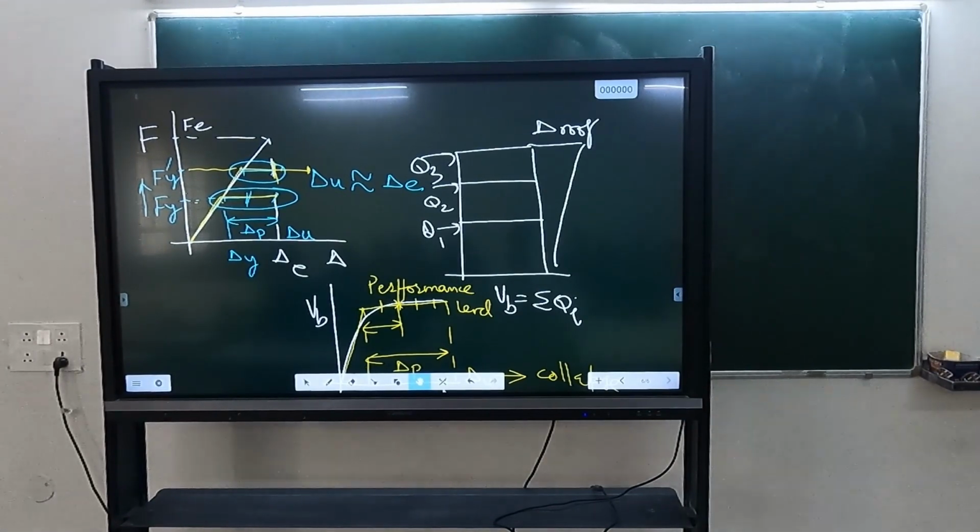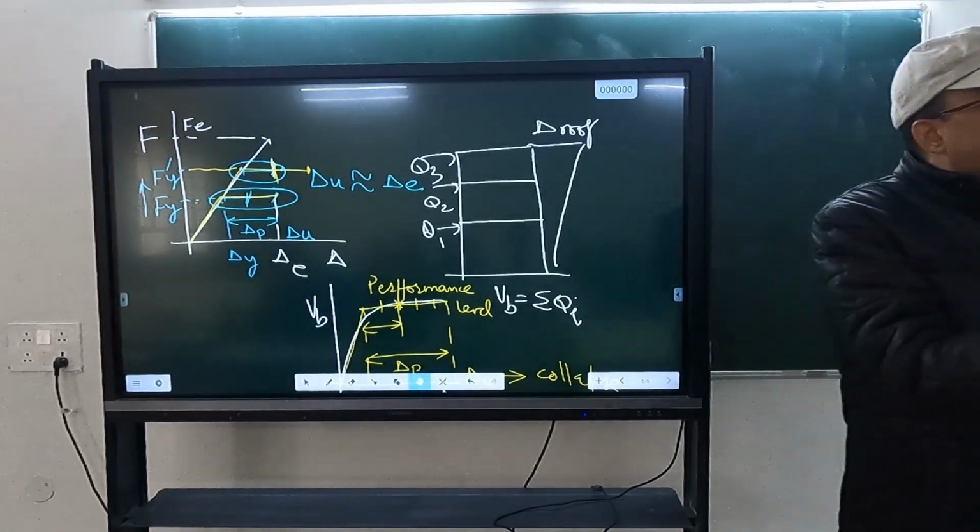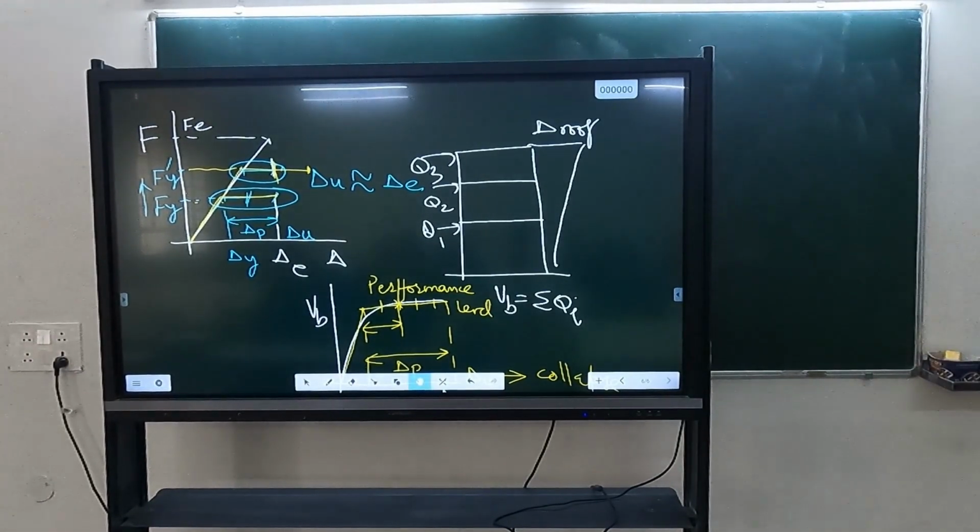In a hospital, you have both. So what is the solution? We have to find a balance. How? There are two contradictory requirements. In that case, base isolation or dampers are the solution. Suppose you are not able to come out with an optimum stiffness which controls drift as well as acceleration, keeping both within limits.